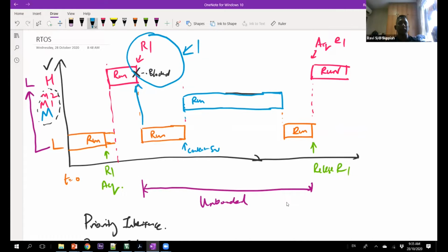Okay, so this is called the priority inheritance protocol. In the priority ceiling protocol, it is the same idea, but you try to think one step ahead. The moment the low priority task acquires a resource that is shared by a high priority task, it is automatically raised to the priority of the matching task, even though the matching task has not been blocked yet.